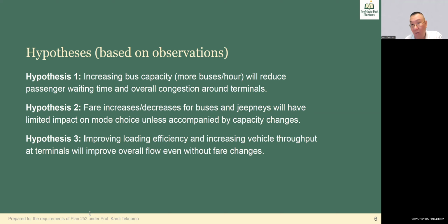Is that correct? In one movement, and you said a while ago, like 8 every 10 minutes, right? That means, say you have 5 or 6 trains, each with 4 cars. So that means you will have 1,400 capacity, multiplied by, say, 5, right? That's around how much? 7,000 plus, right? But your number of passengers was only 1,600. That is very small. Correct or not? Comparing the demand to the capacity, the supply. So your number does not match.